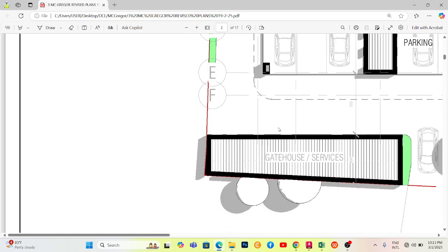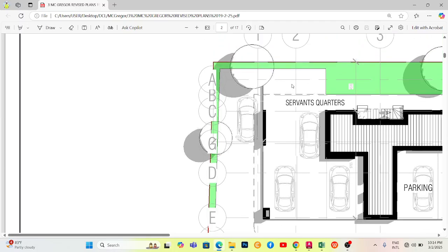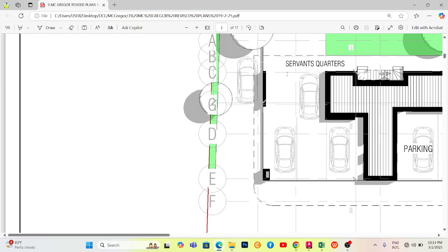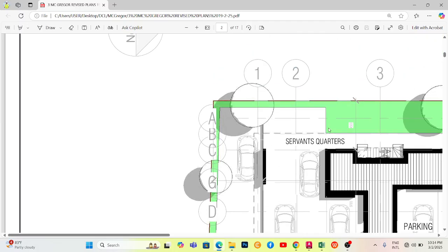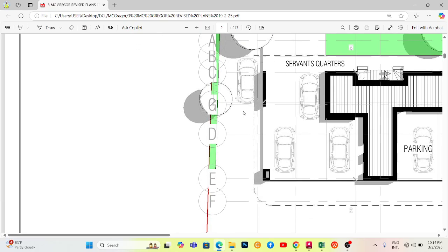I will superimpose this drawing on the layout, in the boundary that I picked on site as well. So I can use their design boundary and superimpose it with my existing boundary. Do you get what I'm saying? So that we can then check. Once I've done that, I will check if what they designed will fit in with what is existing on site. That is very, very important as a surveyor.